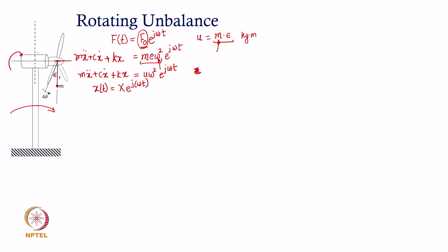In any case, this unbalanced force can either generate a vertical translatory or harmonic force, or it can generate a harmonic torsional excitation, or it can generate a harmonic moment, and so on. So, whichever way you model this vibratory system, the excitation still is harmonic, and thus the process of investigation is still the same.